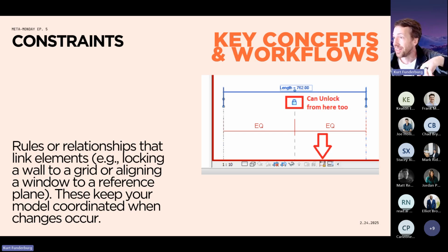Maybe we want to darken the line, so we draw plywood in. And then maybe there are some bracketing details that we need to show right above the header of the window. That's where we'd start to add that information, where you'd see the bracket, but you need to see a bolt go through there and where the lag is and all that. So that's the level of detail that you go to with the detail view.